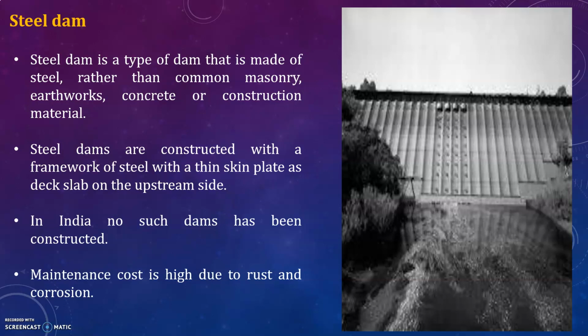A steel dam requires greater and more constant maintenance than concrete. They have to be anchored at foundation, which is difficult and precarious. And also there is considerable concentration of bearing stresses. So this is about steel dams.